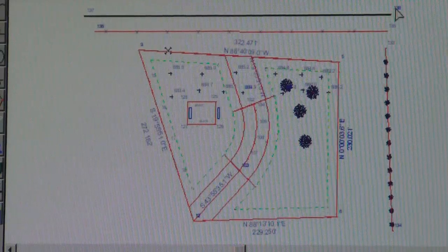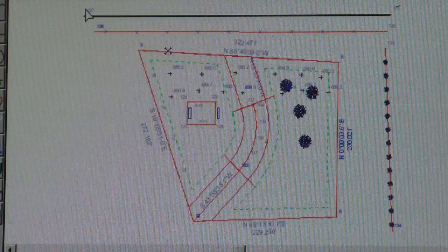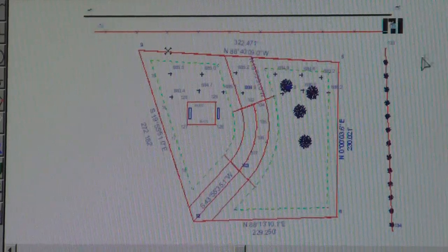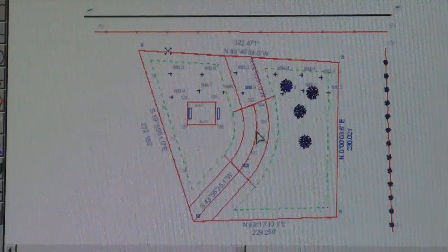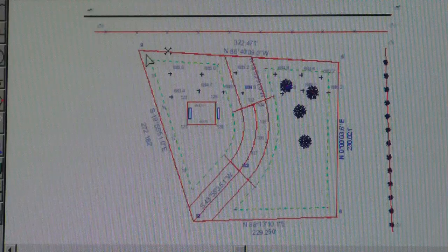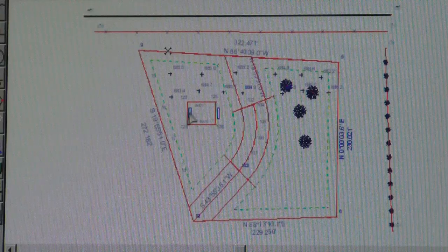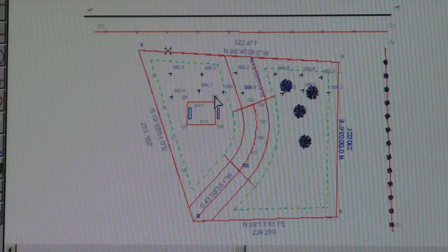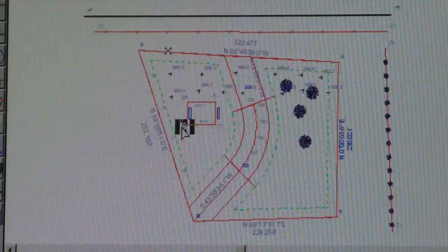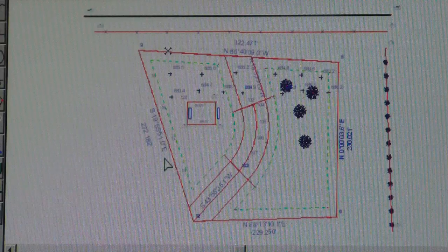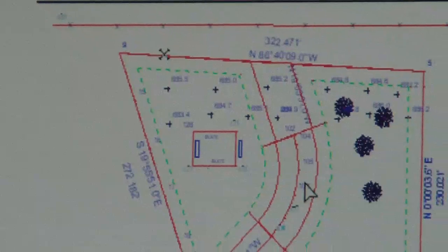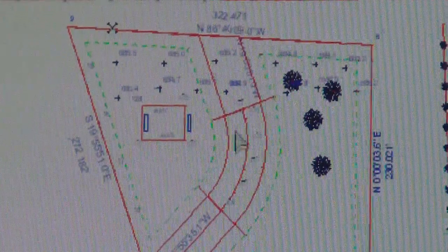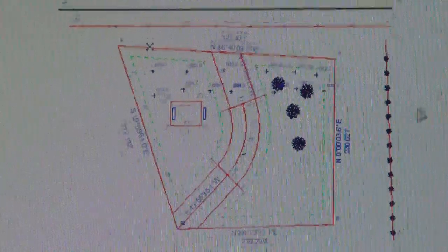Now once you have like edge of pavement, I would normally go in and delete the point numbers and the fence. I would get rid of that, the tree line numbers. We don't need those. The only thing you really need point numbers for is your traverse. And you will need one building corner, because I think you're supposed to locate that by 2 corners. I would dimension the building. The 4 points on a straight line, after you do that particular lab, you can erase those. You can actually get rid of all the points on the curve. Those are rarely shown on drawings.